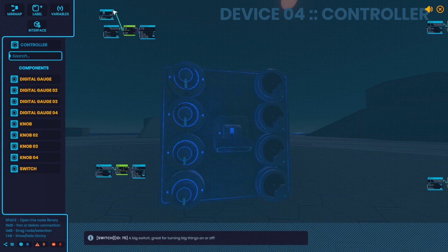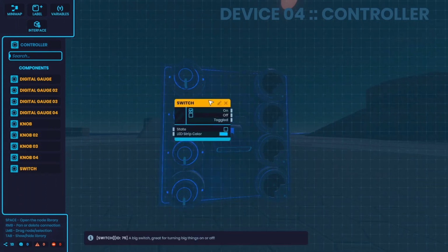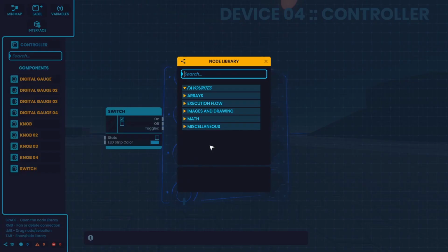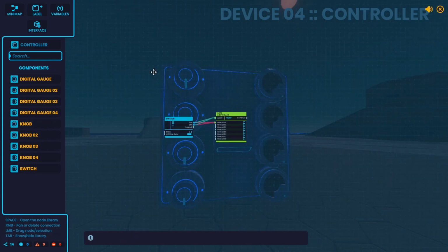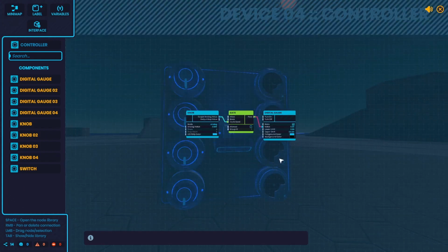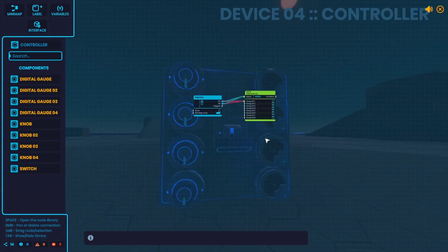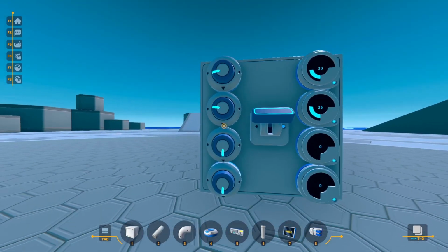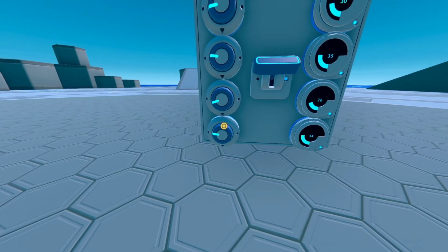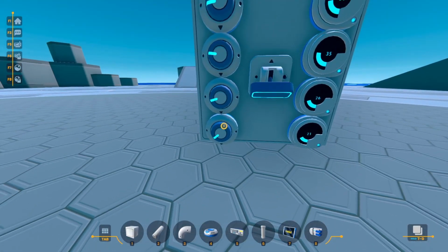So this is where the gate controller comes in. So now, anywhere in your sketch, you can just grab a switch, and grab a gate controller, and set it just like that. And also you want to apply it every time it changes. You got to make sure you use the correct group ID. All of these gates are 1, so this should work great. So now when I turn the switch on, they should all show the value. When I turn it off, it should block the values.